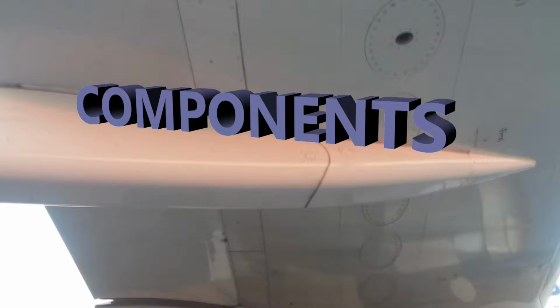You also have a magnetic indicating. This is on ground only. When the plane is on the ground, there's a magnetic level indicating mechanism there, and it's pretty mechanical, but it's magnetic. But it's measuring the fuel for all of the tanks. And because it runs on magnetic, you're not having to run electrical power to it. You're just using the mechanism there with the magnetism.